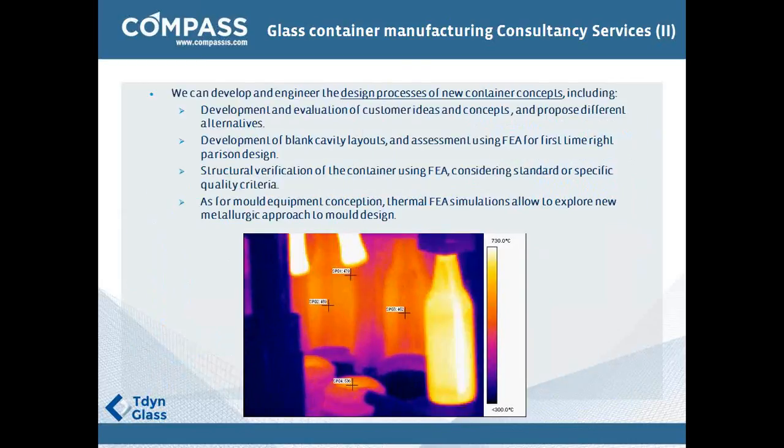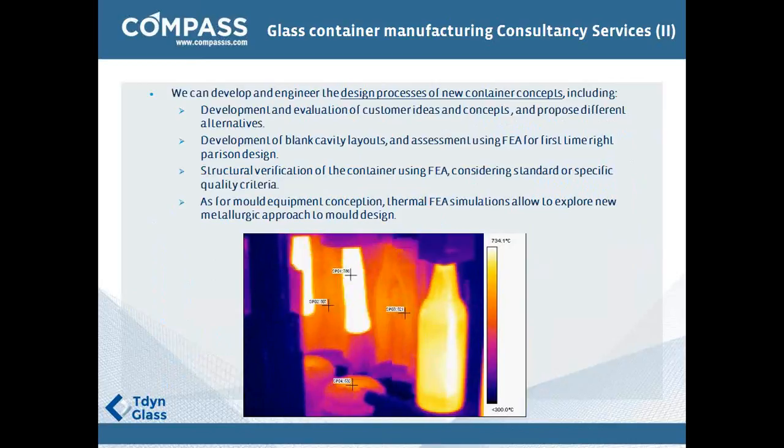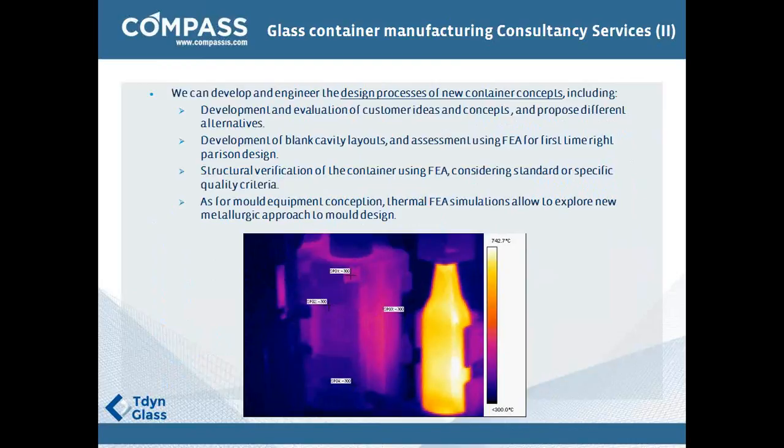These consultancy services, we think, can help in the evaluation of customers' new concepts, as for example the development of blank cavity layouts, or Parison design assessment by means of finite element analysis. Finite element analysis will also be used to provide assessment for structural verification of containers in order to match quality criteria, and for mold equipment conception, performing thermal simulations.